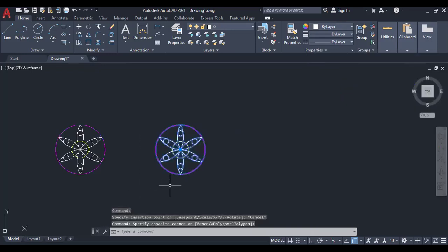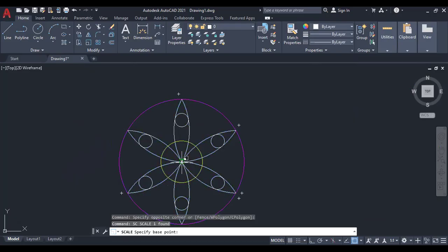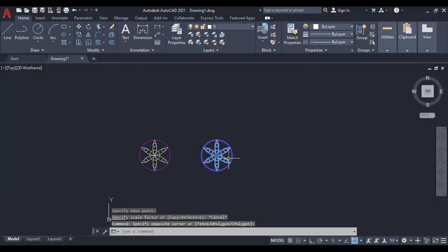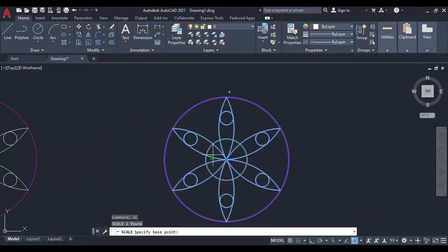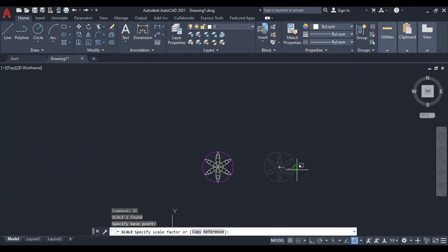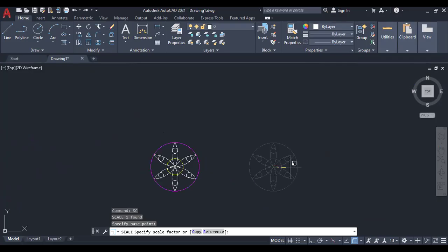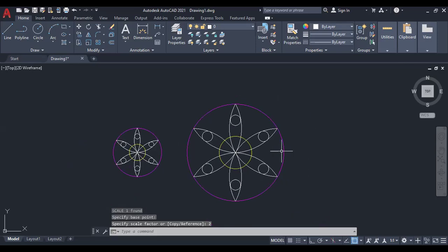Now what I'll do is I'll select whatever block I have done. Okay. You can scale it easily like this. I am selecting this. I'll go to the command called scale. That command code is SC enter. I'm selecting the base. Okay. So I am giving the factor. You see, you can increase how much you want. This you can scale, or else you can give the factor. I'll give 2, enter. See, it will become exact double of the previous one.